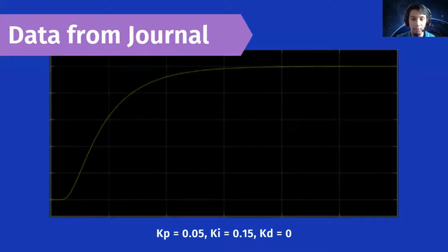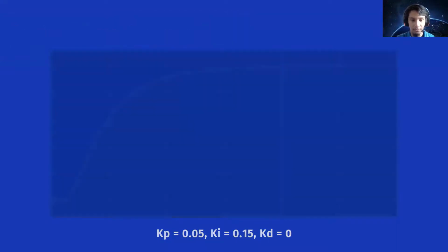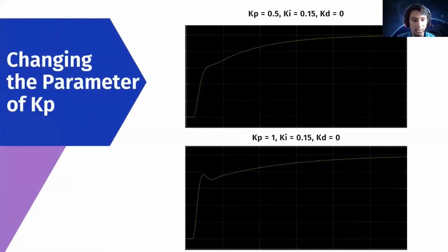However, the effect of each controller contained in the PID controller can be observed by the changing of parameter of the components involved. So first, for our project, we are changing the parameters of KP, which is the proportion parameter, and the value is changed from 0.05 to 0.5. The system response is increased by achieving 0.5135 in 2.217 seconds, while the normal condition achieved the value of 0.5065